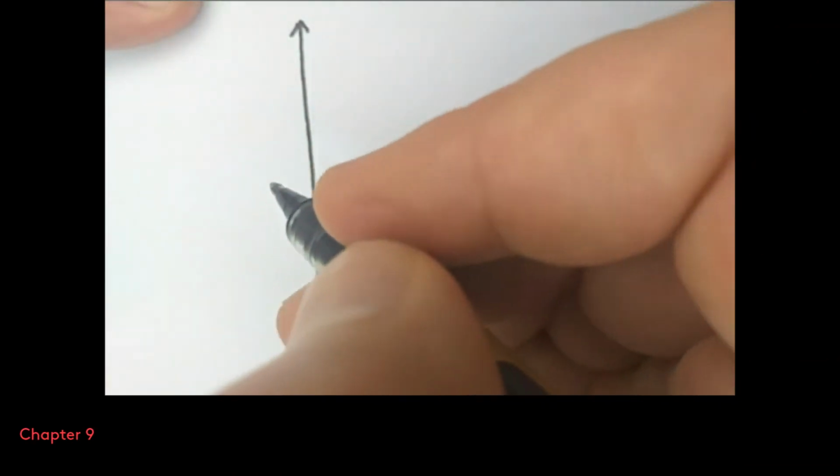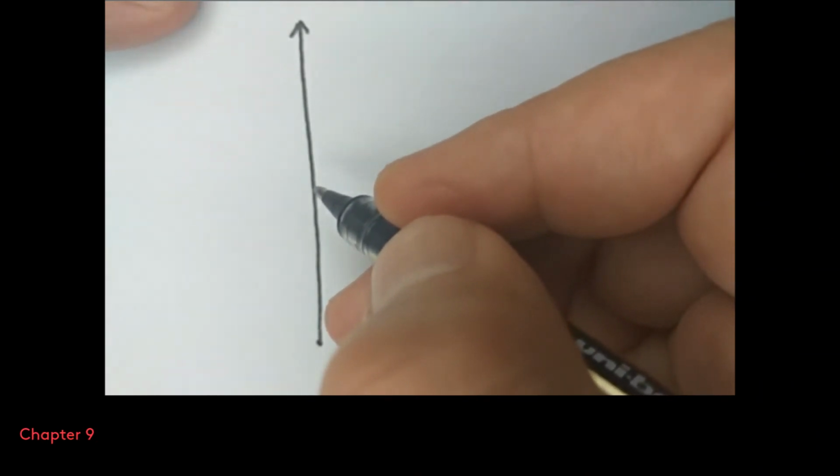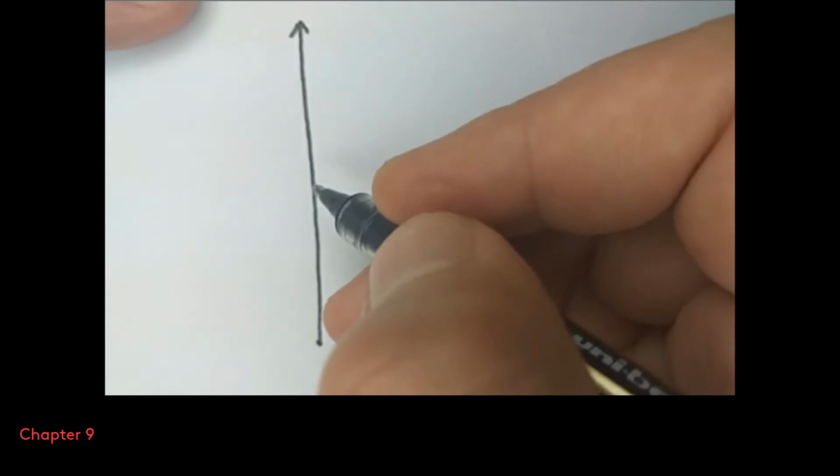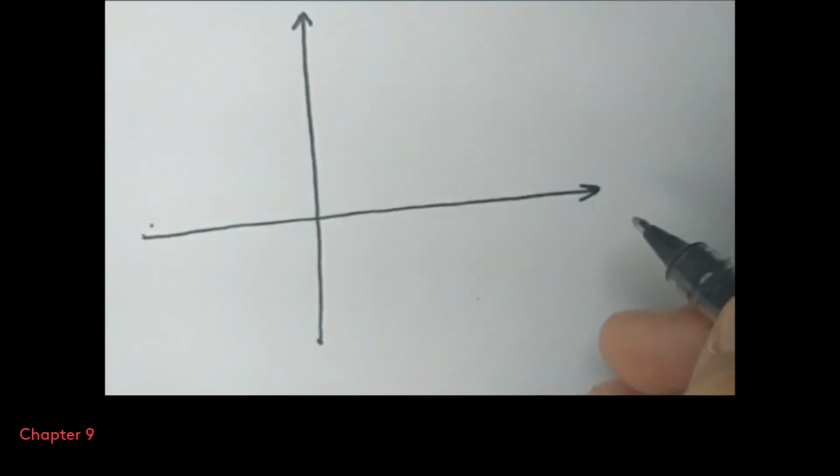So what if, in order to determine the state at a point by means of stress, I use a coordinate system which has the stress values as its coordinates? On one axis I have the normal stress, and on the other axis I have the shear stress.